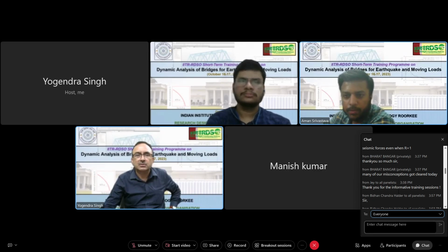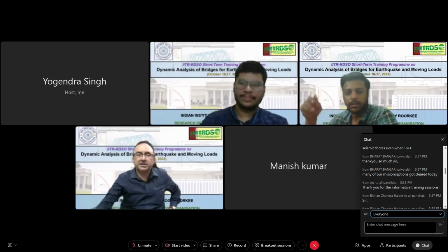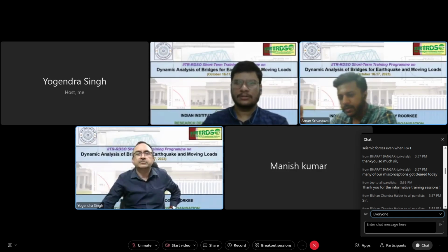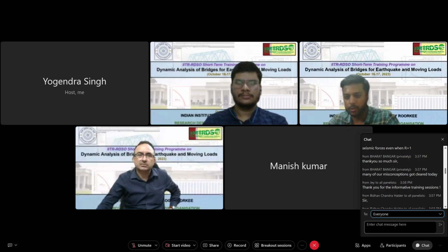Okay, sir. And Sugandha is asking, while amplitude scaling to the code spectrum, shouldn't we also check the rotated ground motions to match the spectrum, as it is not necessary that the maximum PGA during an earthquake event occurs in the orthogonal direction in which the ground motion is recorded? Again, the question is not very clear, but what I understand is that it is regarding RotD100 and RotD50. The recording of the ground motion is in two orthogonal directions, but the maximum or the original ground motion will not be in that direction.